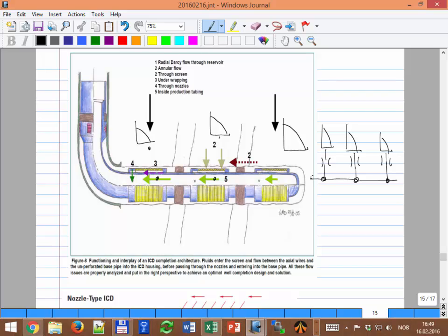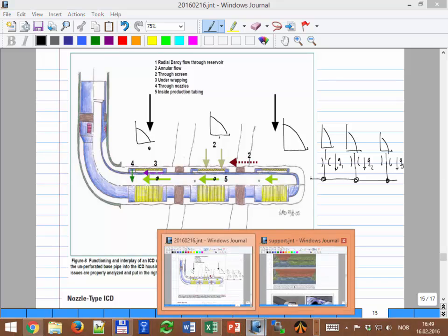Then here we go to the wellbore. So again, we have to do solving. We have to assume a rate through each one of them. Maybe we will do one example, or that will be the homework. You have to assume rates for each one of them, and then say that the pressure here is the same whether I calculate it from here, or from here, or from here. Basically the same thing as a network. You have to solve the network to find the operating rate. I think I don't have any more nice pictures.